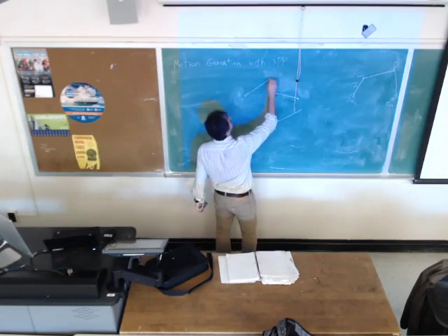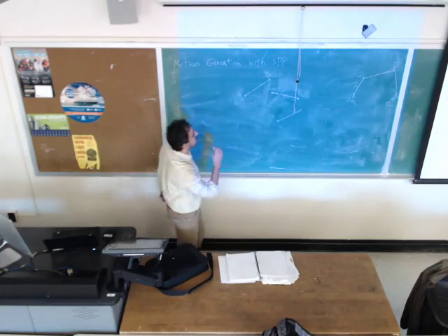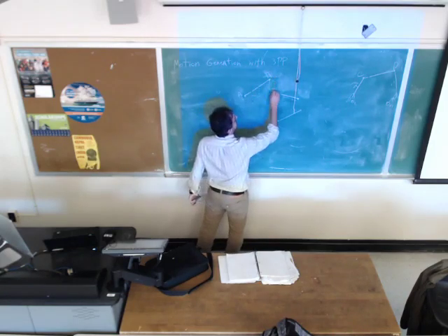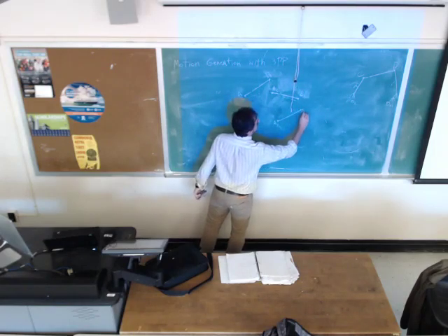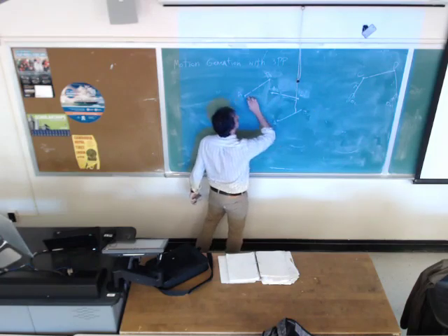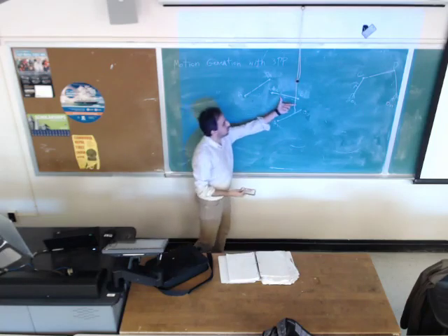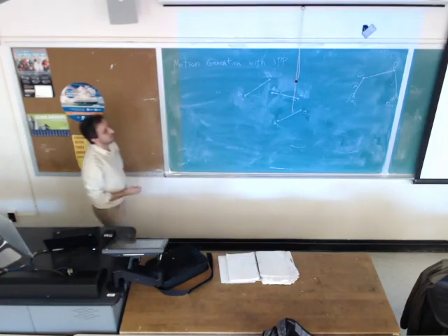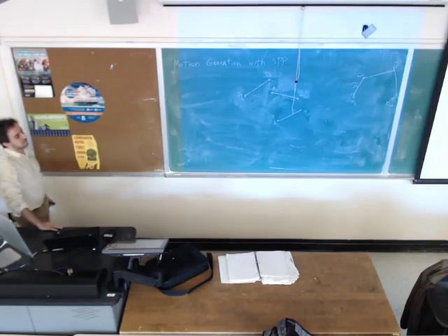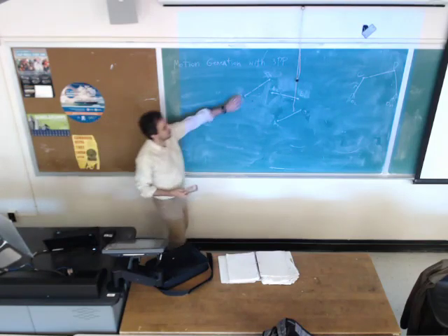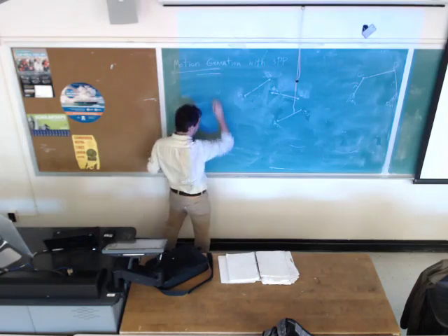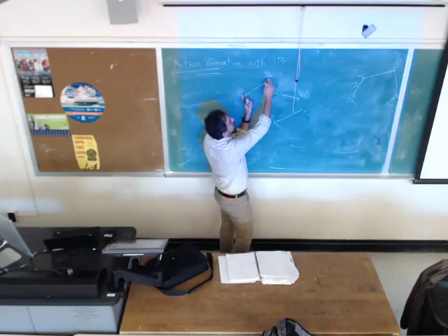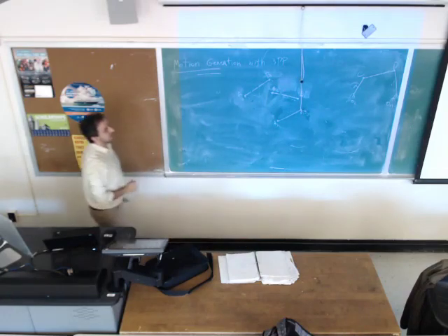Suppose I have link or rigid body AB. I would like to move it through these three precision points: from A1 B1 to A2 B2, and the third one is A3 B3. It's a motion generation because it's talking about the motion of a rigid body. And it's three precision points because we are given three desired locations.